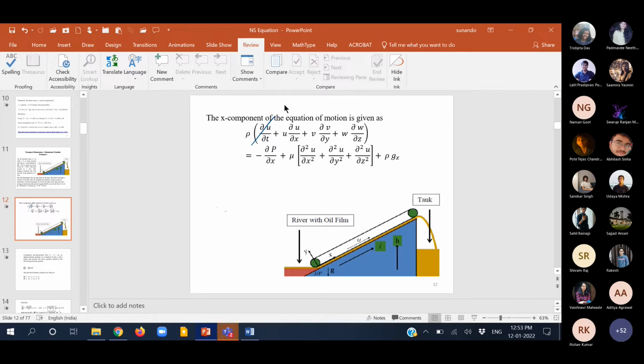Laminar. Not laminar. Say in this region, at the entry point, u may not be a function of y alone. It could be a function of x, but beyond some x, after it traverses some distance, it's going to be only a function of y, not a function of x. So that has a special name to it. Do you recall that?